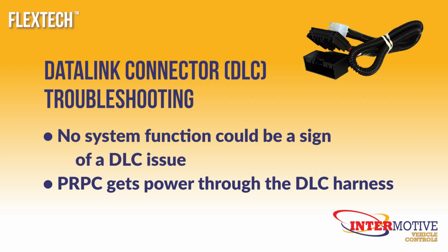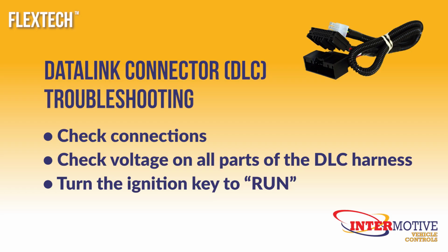Data link connector troubleshooting. The sign of a DLC harness issue is absolutely no system function. The PRPC gets its power through the DLC harness. Check all DLC connections and voltage.